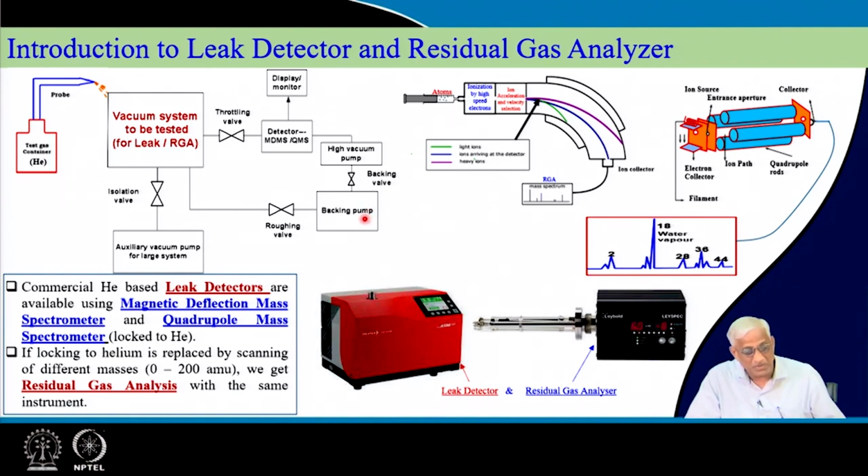And this backing pump, which was originally the backing of the detector vacuum pump, can also be used to evacuate if this volume is smaller, because the vacuum pumping system attached to the detector is relatively small, but high vacuum. It also has a turbomolecular pump, and a background dry pump or rotary pump, but capacities are not much. Its purpose is to keep the detector in good vacuum condition, but you can use this to rough it, provided the system is small. When will that happen? Component testing.